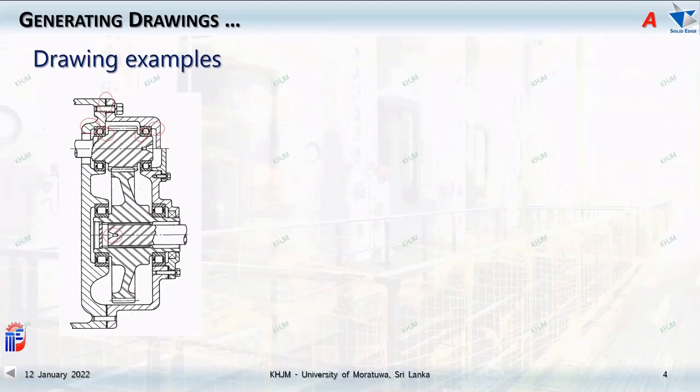That side you have a clearance. And if it is the other way around, meaning the depth of the end cap is greater than the bearing width, then this end will contact the housing and be tightened the maximum possible, but still there will be a clearance.